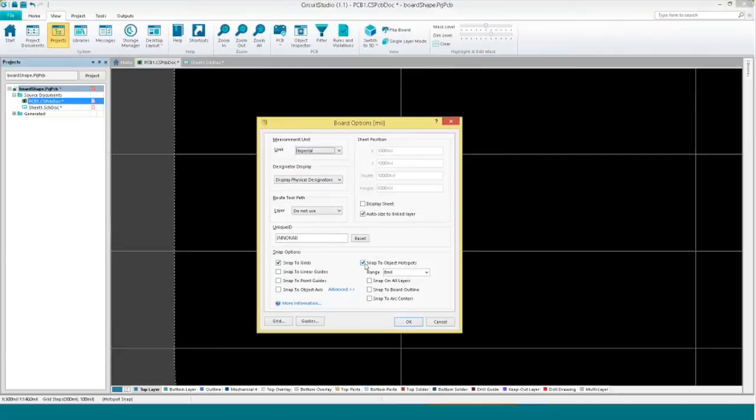A lot of times I see people use a coarser grid when they're aligning components, and then they switch to a finer grid to actually do the routing. Sometimes they'll even set the snap grid to the sum of the width of their signal tracks and their clearance. Like if they have a 5 mil track and a 5 mil clearance, they'll set a value of 10 to automatically follow those clearances on the grid.